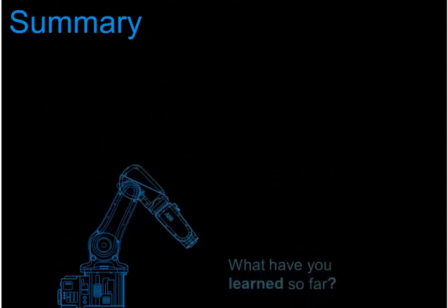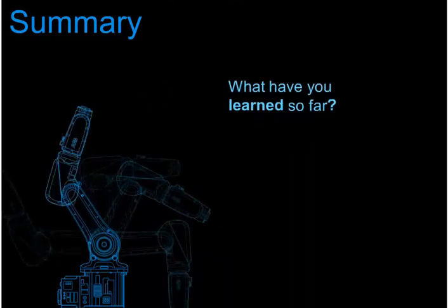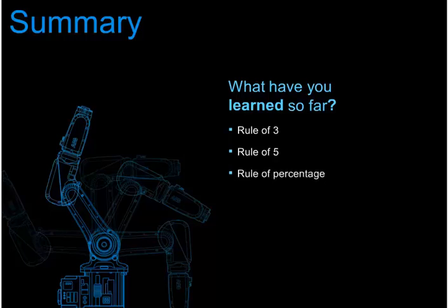What have you learned so far? Each WirelessHART device needs 3 good neighbors in effective range. Each WirelessHART network needs 5 devices in effective range of the gateway. Each WirelessHART network shall have at least 25% of devices in effective range of the gateway. WirelessHART transmitters with update rates faster than 2 seconds must be within 2 times the effective range of the gateway. So far so good?